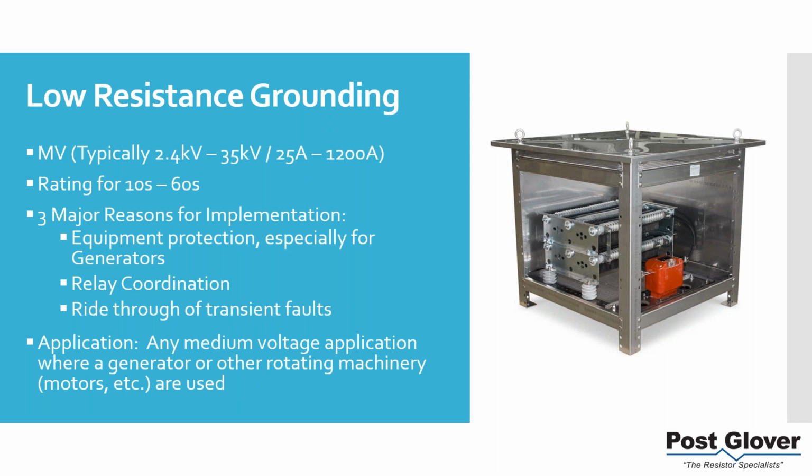I say this especially for generators. In fact, IEEE recommends that a medium voltage generator should have impedance ground on the system, and the vast majority of those for industrial purposes are going to be resistors.